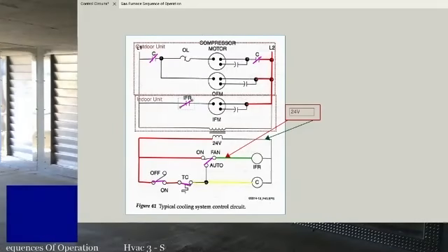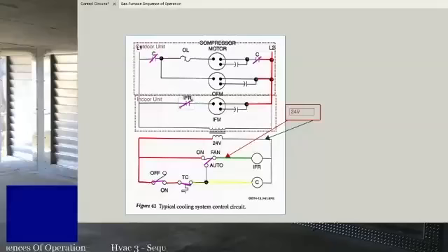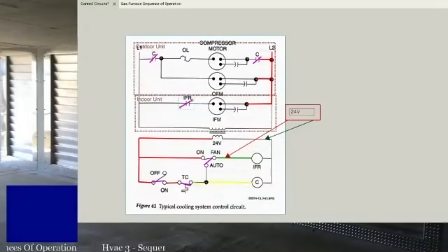So right now we've got a fan motor that's not running. We're not talking about troubleshooting cooling problems. But, well, I guess let me step back. If the fan motor's not running, your coil will freeze over. But we know the fan motor's not running. So the point is what's causing that fan motor not to run. So one thing could be that something's wrong with the relay. Either the coil is bad or the contacts aren't properly closing. What other issues could we have?